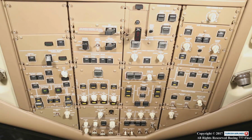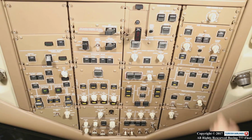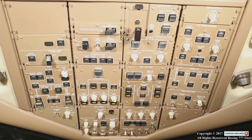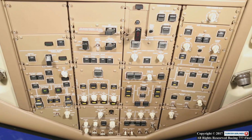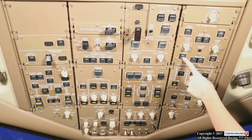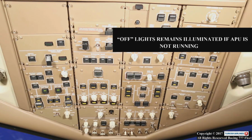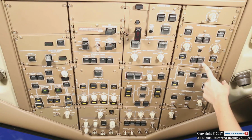Recirculation fan switches, on. Flight deck temperature control, mid auto position. Cabin temperature control, mid position. Pack switches, auto. Verify the off lights are extinguished. Trim air switches, on. Verify the valve lights are extinguished.